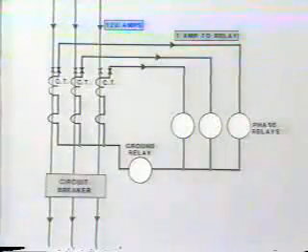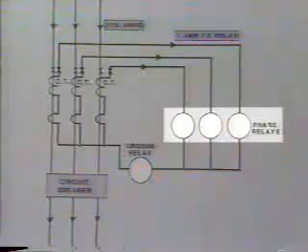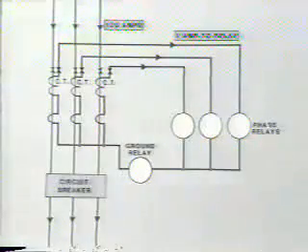Of course, the circuit that we have been studying is extremely simple, and we have not specified any particular type of relay. You know that this is going to get far more complicated as we go along. For example, considering the three phases of the same circuit, we now have to include 3 relays, 1 per phase, plus a ground relay, all with their separate CTs and sometimes VTs as well.